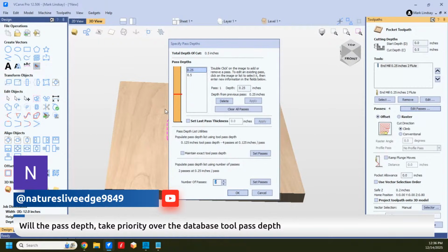You're pushing that bit through, in this case, a 1/4 inch of material per pass to remove that material quickly and get that 1/2 inch pocket cut in 2 passes. The problem comes when you're down at the bottom pass. When you look at the bottom surface of your material and you think, well, that could look cleaner, but there are some tool marks.